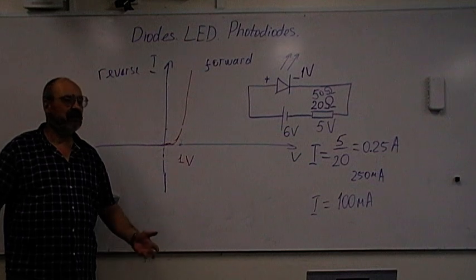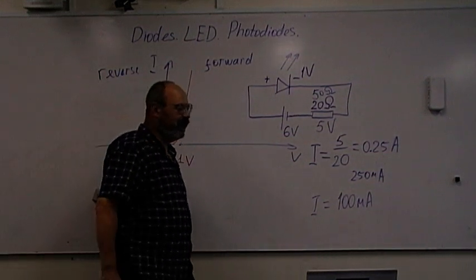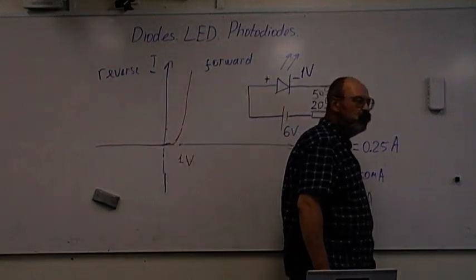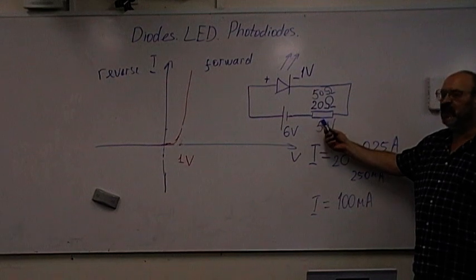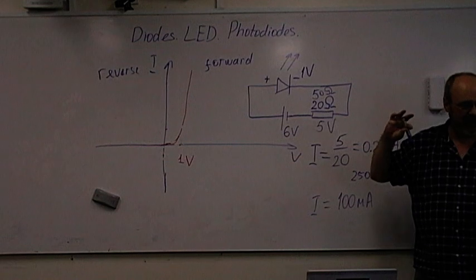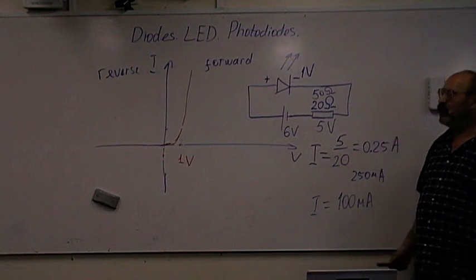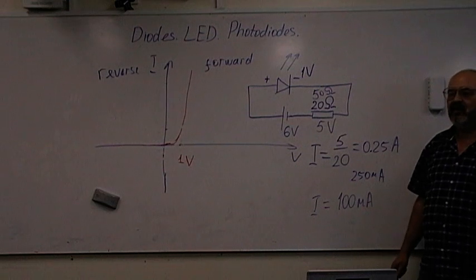It will melt or burn out. That's what students sometimes do, because you will be doing prep with LEDs. They forget to connect this limiting resistor needed to limit the current, and they burn LEDs. So this one is needed to limit the current through the LED.